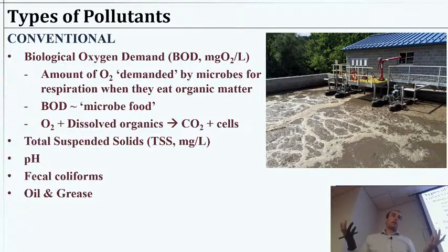And that's actually exactly how we measure it. We'll go through some of the math. It's pretty simple. But that's what BOD is. That's what our biological oxygen demand is. It is a measurement of bacteria food. And we're measuring it based on how much they're breathing, because when they eat, this is essentially the process.